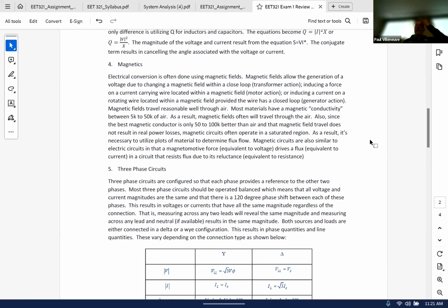So understanding how we have reluctance and air gap, because in transformers, there's no air gap. All the windings are on top of each other, and then they're on the core that's solid. But in motors and generators, we have to deal with air gaps. Anybody want to guess why? If there's no air gap, wouldn't the rotating part and the stationary part be touching each other?